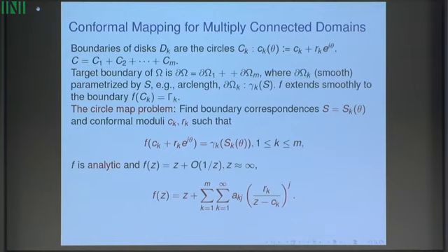Maybe you just have a bunch of points, like a NACA airfoil. That's basically what they give, and you run a periodic cubic spline through. So you need some parameterization of the boundary, because the conformal mapping method has to make a guess for the boundary correspondence, and then kind of move tangent until these things are the boundary values of an analytic function.